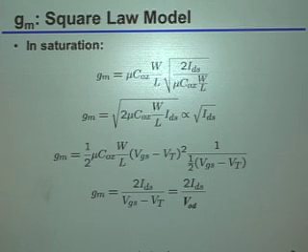Okay, great. So if there's no questions, then let's again start out by looking at the transconductance, because we'll see that actually most of our design procedure is really going to be driven by understanding transconductance. Okay? So here I'm just showing you a fairly classic form for what the GM actually is as a function of the bias current for a long channel or really square law device.